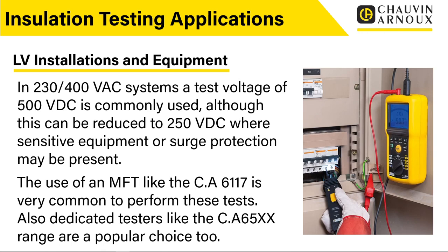Quite often people like having a separate insulation continuity tester because it's a bit quicker and easier to use. Somebody can carry out testing using that while somebody else is using a multifunction tester to do other things. They are quite popular, particularly if you're doing specific types of maintenance work, where you're not doing full electrical installation certificates and full tests all the while, but you might be doing bits of fault finding where carrying out insulation resistance testing is useful.